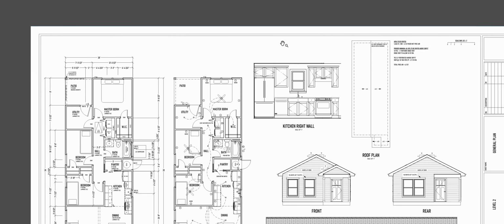We just got done with the gravity design for this house, so we are going to move into the lateral design. The first thing we got to do here is determine where we are building this thing because we kind of need to know if it's a seismic category or a wind category, what's going to determine our design. For the purposes of what I'm going to do here, I'm just going to say that I happen to be designing by the wind. There are no seismic problems, therefore I'm going to design by wind speed, and I'm going to say my design wind speed is going to be 115 miles per hour.